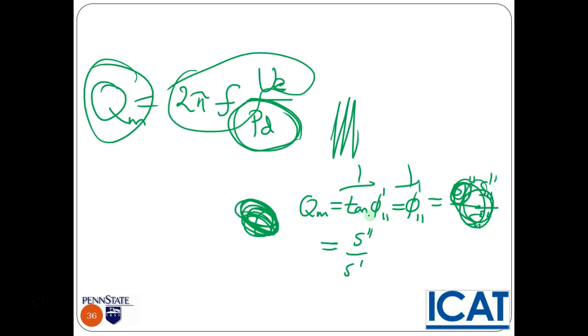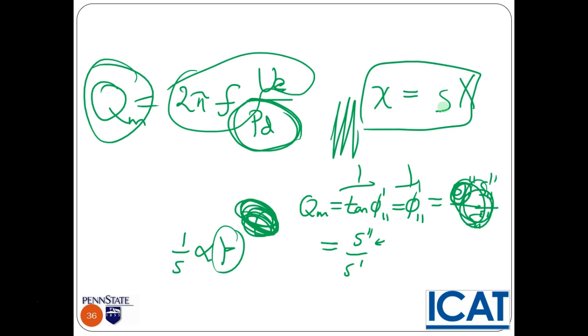This is sort of backward from how we normally think about it, because the compliance is 1 over the spring constant, which is tied to Young's modulus, and Young's modulus is usually what we think about to measure energy, and that's more natural. But if you want to talk about inputs and outputs, compliance has to be the input, because you apply stress, you don't apply strain. So this is stress and this is strain.